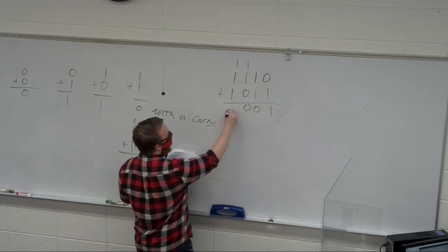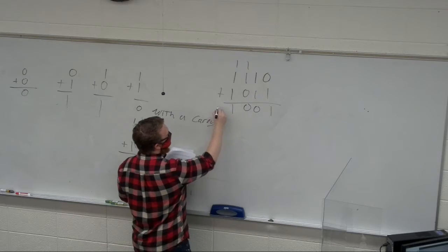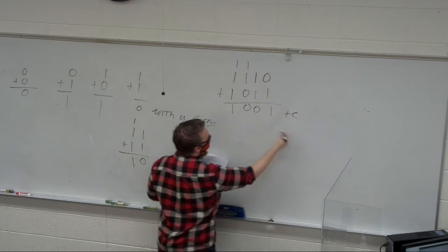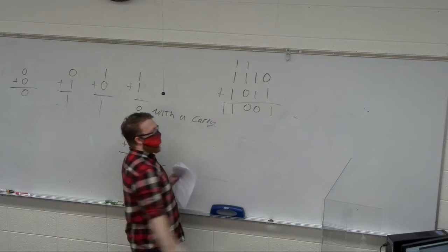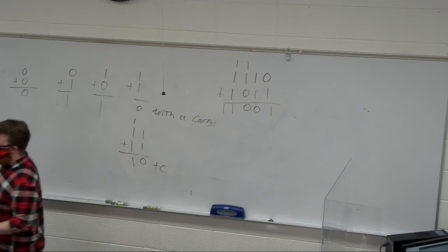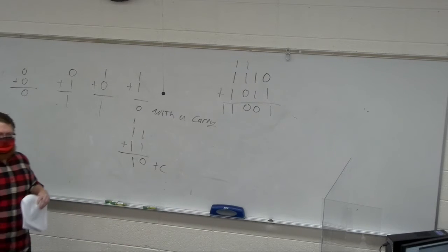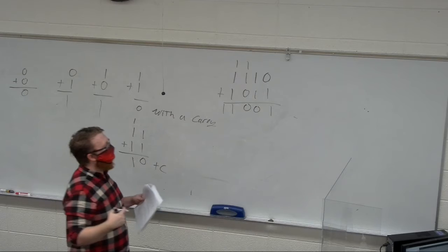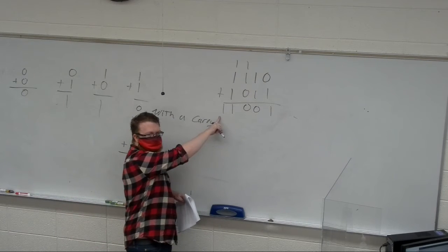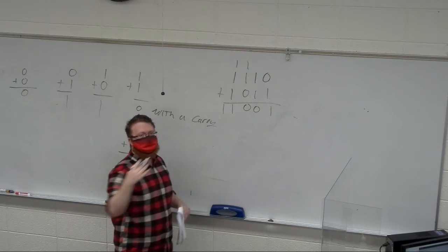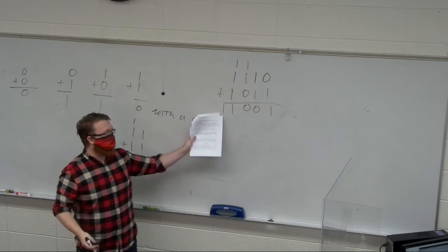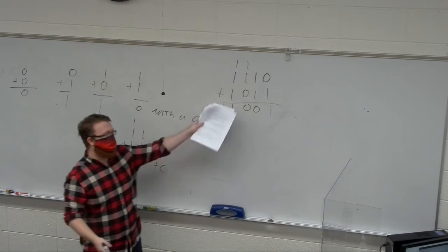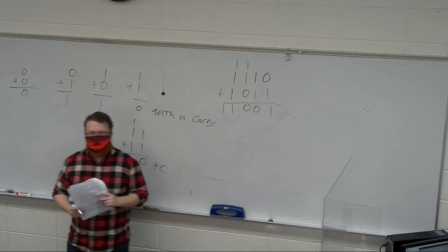And now I have 1 with a carry. Since they asked us to have a 5-bit output, we'll just take the carry over. So it turns out our carry, we call this a carry out, can be used as our largest bit, our MSB. And it will never add to anything, so we can just use it directly because we're adding 4 bits and this is a 5-bit slot.